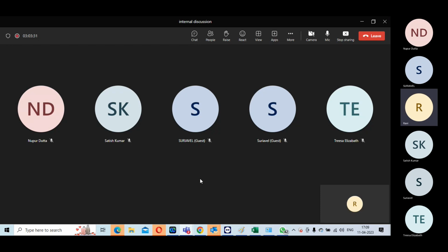Like this, I have got so many options. Mainly out of the chief preference. See, it depends on what you are doing here. Let me say tomorrow is my tapeout. Today I have to do it. I have only 5 picoseconds. If I just swap to HVT, LVT, my design is done. I don't have to touch DRC. Otherwise, I have to route, I have to run every damn thing, it's a problem, no? So it depends on which stage you are at, what is the critical problem you are facing at that point. These are options. There's no golden rule that you should only do this.